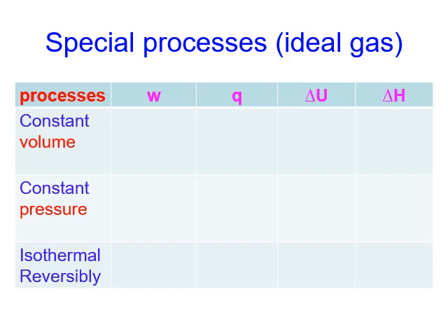What is work under constant volume? Volume doesn't change, so work is 0. What about constant pressure? The equation is negative pressure times volume change. The isothermal reversible equation is negative nRT ln V2 over V1. So work is path dependent. You must know the path, whether it's constant volume, constant pressure, or isothermal reversible, to choose the correct equation.